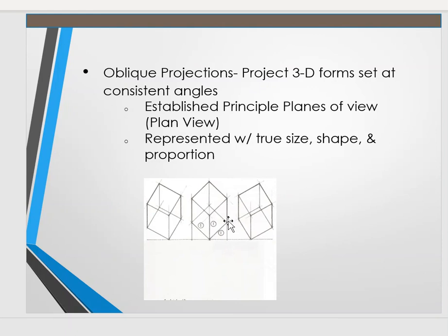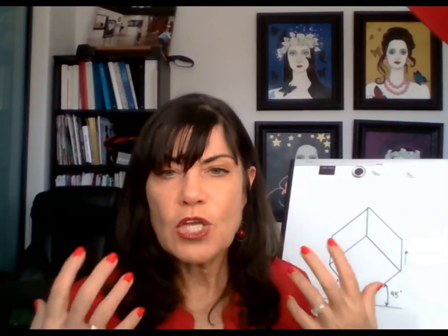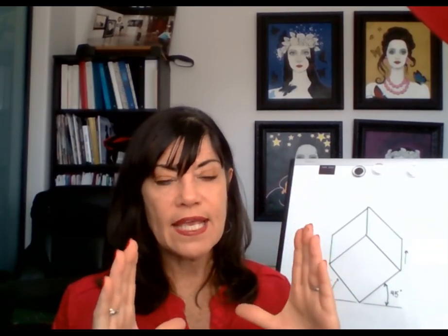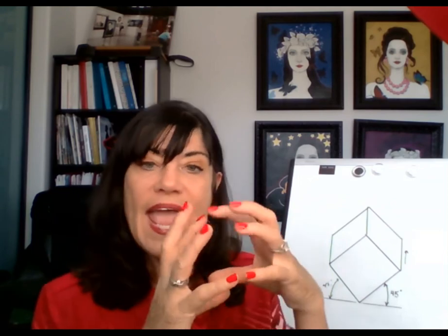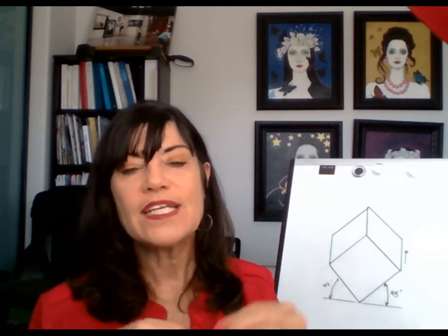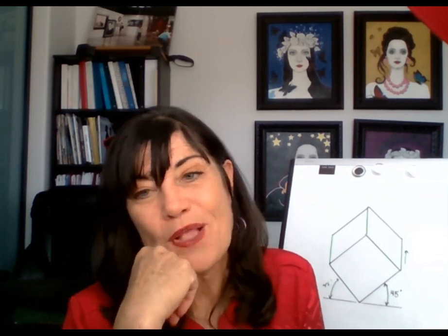Like I did with my cube just now, I just put the cube at perfect angles. I brought up lines because I knew the height of the cube and I connected the dots. Here, it's just at a slight different angle, like I just showed you on my other rectangle, vertical lines, and you connect the dots. We'll be doing simple objects like this in class so that you can get that understanding of how to take a plan view or an elevation and elongate it to create a three-dimensional object.